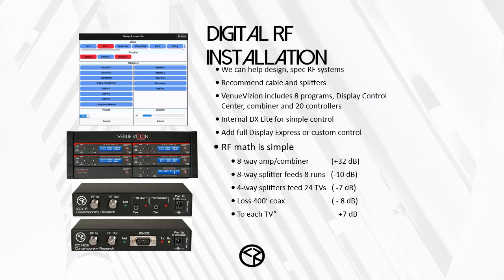So you measure how long it takes to get from the system out to the TV approximately, and work on your worst case scenario, because that will have the most loss, and all the rest are going to have more power available to them. So let's say this drops 8 dB, which in this case we're figuring at, over 400 feet, we lose about 2 dB per channel, because we just have really 4 channels in this system. So that's -8. So when you subtract all the losses, that means each TV is going to get about 7 dB. And we like to put our thumb on it.